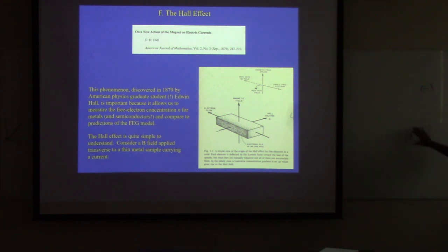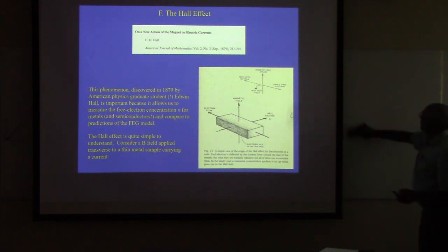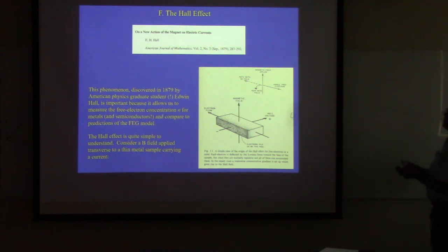When you have this kind of p or n material, the Hall measurement is the easiest and most direct method to quickly test whether it's p or n-type. That's why the Hall effect is so useful to identify the carrier type and also the carrier concentration, n. Remember, typically p is for the holes in p-type materials.